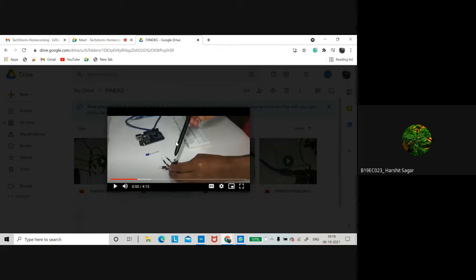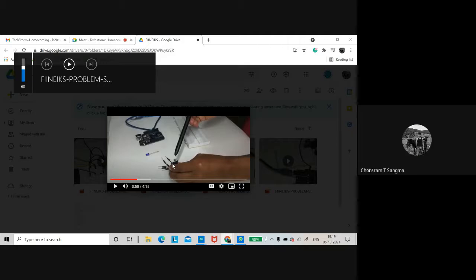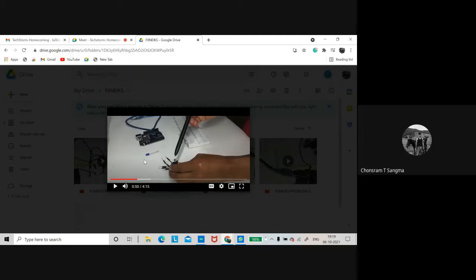So this is your LED or photoresistor? This is the LDR, and this is my LED. LED and photoresistor are both different things. One works as our ordinary lights, and the other, the LED, is the light emitting diode. Yes, a photoresistor cannot emit light. Okay, now you can proceed. When the brightness is very high, the resistance of this photoresistor will be small, sir.